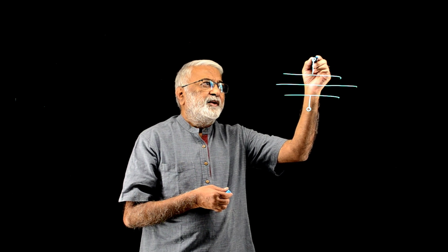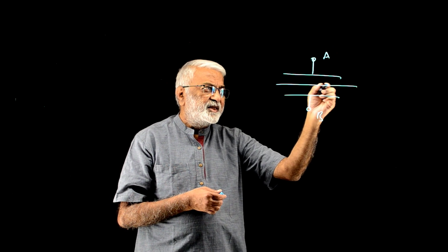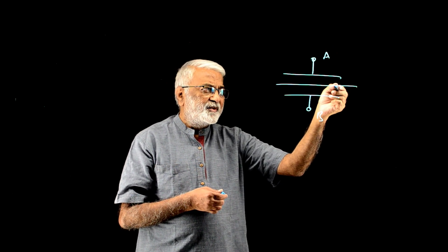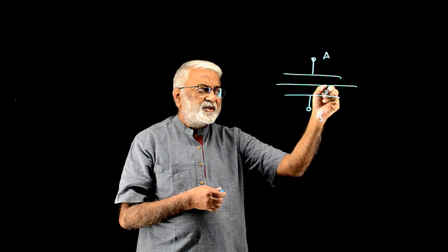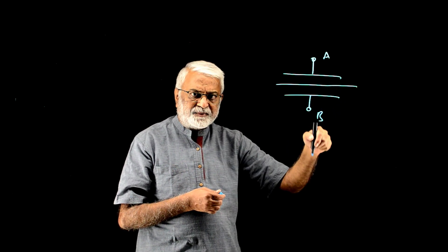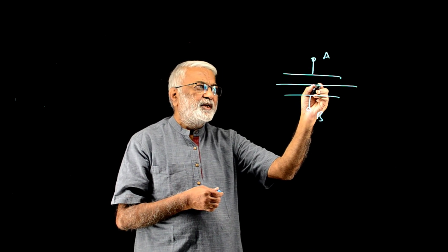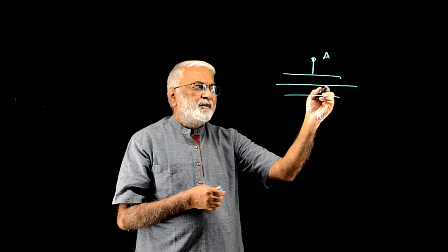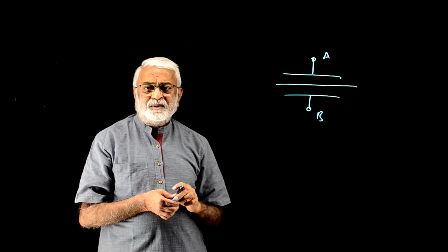Now one way of seeing this, you saw this in terms of the field earlier. Now we're going to see it as what? We have a charge flowing in here, inducing a charge on this surface. This is the sum total of the charge, and this must be 0. There will be negative charge on this, and that will induce a positive charge here, and negative charge leaves, positive charge leaves through this, making it negative. So Q here, minus Q here, plus Q here, and minus Q here. Just like a series capacitor, right?